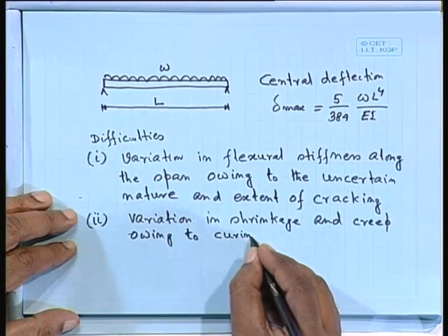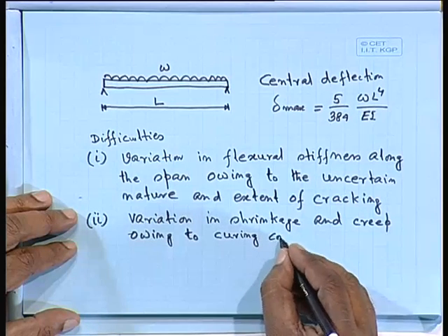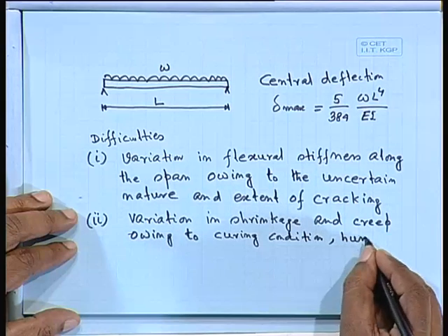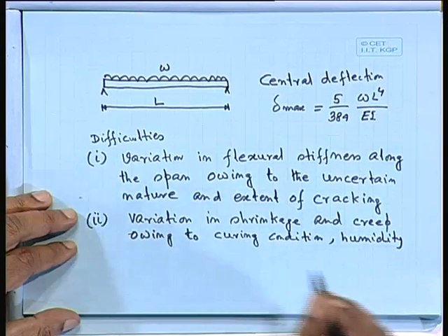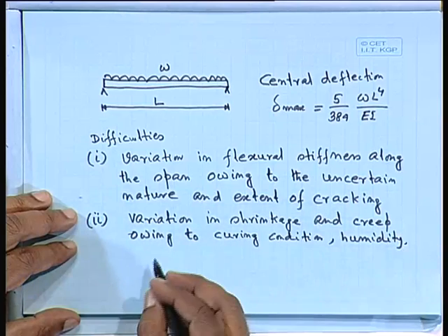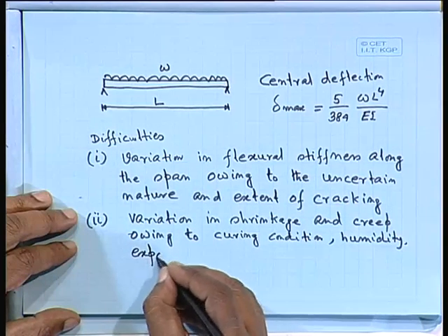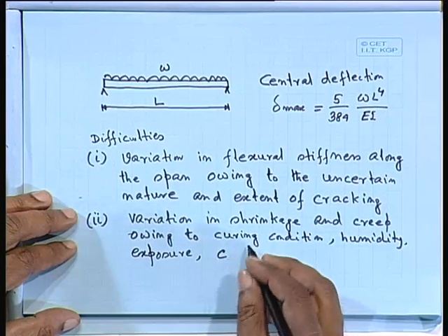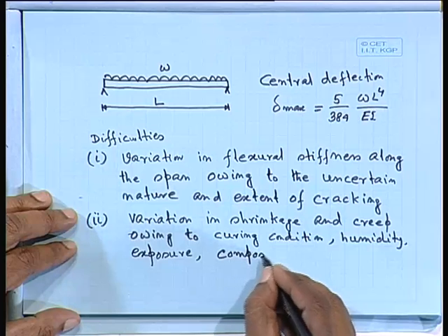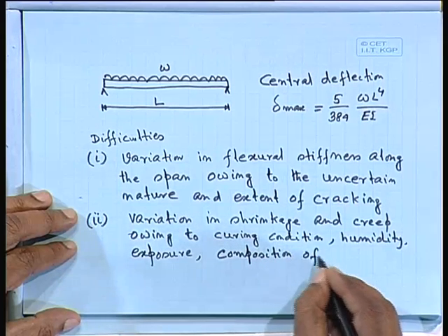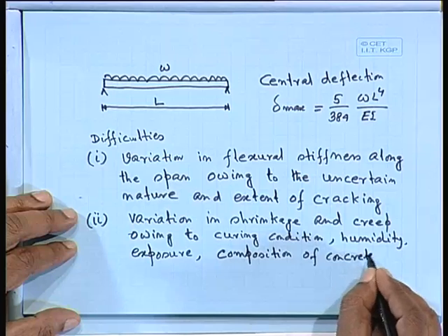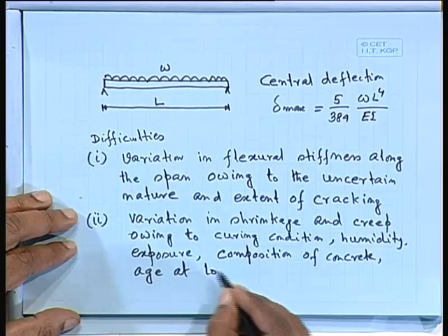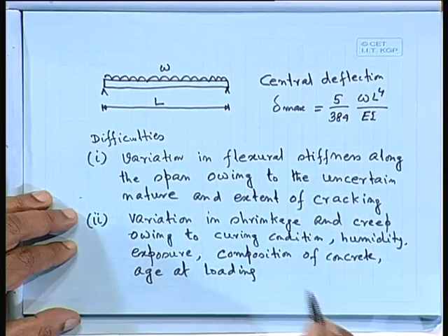It may happen due to curing, how you have cured, then humidity, exposure, composition of concrete, and also age at loading, that is, when you are loading the structure, it depends on that also.